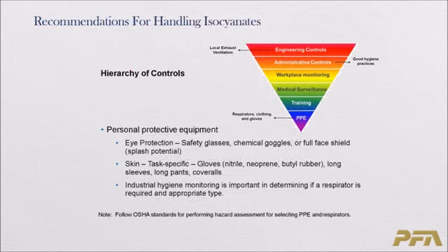The safe way to work with them is through engineering controls, making sure you're working with the proper exhaust and ventilation, good industrial hygiene practices, and lastly, wearing the proper protective safety equipment, the gloves and the goggles. Your occupational safety people can also do some monitoring to determine if you would need to wear a respirator for the application.